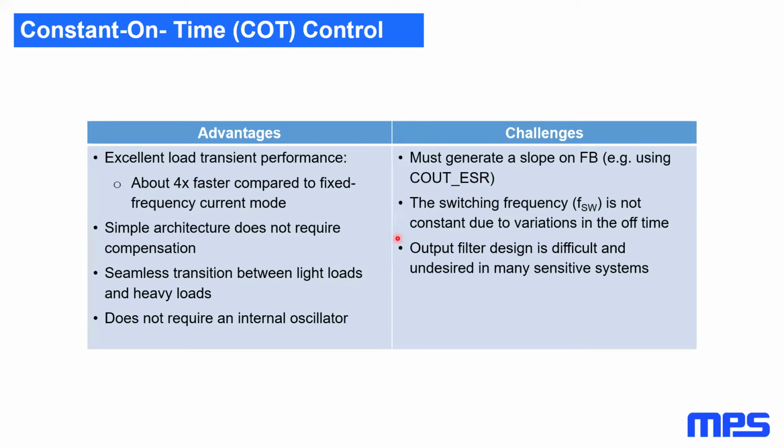our output capacitor. Secondly, the switching frequency is therefore going to depend not only on the output load current, it's also going to depend on the ratio between the input and output voltages. And therefore, this can mean that we can have variations in our switching frequency dependent on, for example, variations in the input voltage. This can be problematic because as engineers, we want to know exactly what frequencies are present in our circuit, and that's already hard enough to do when we have a fixed switching frequency. So variations in the switching frequency is something that we want to minimize.